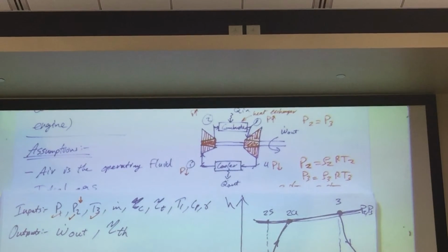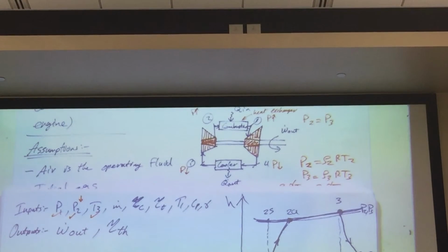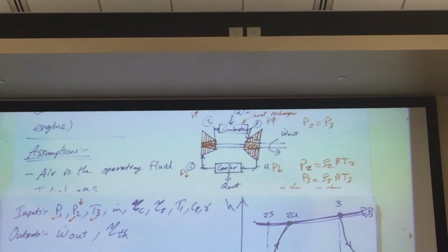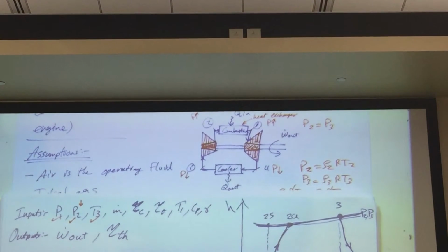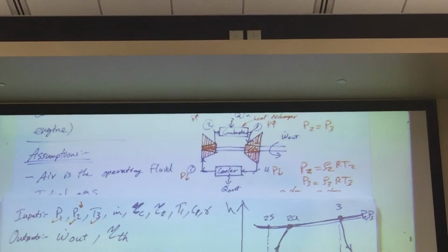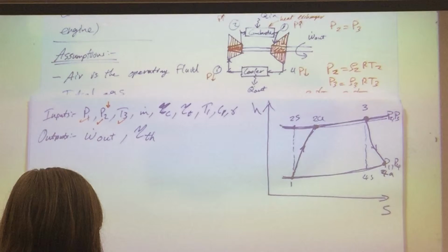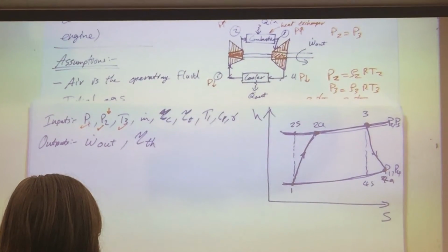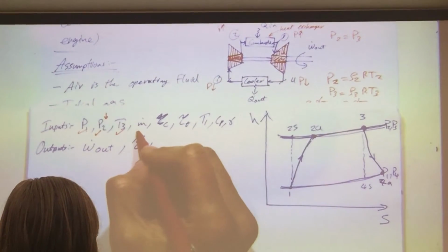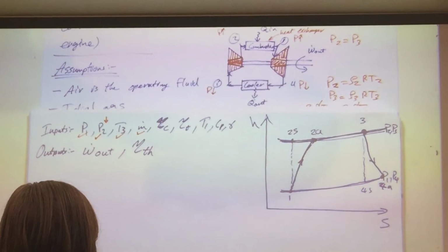Okay, so these are inputs you're deciding. Mass flow. Well, how much mass flow through my system do I want? How do I dictate mass flow? How can you dictate mass flow? Area. Very good. It's m dot equals rho A V. Area, size of the engine. And you're going to do this later on. So you're still the deciding factor of this.